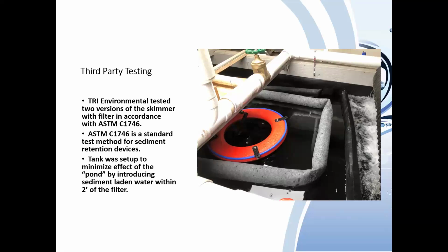You've got a forebay, you've got travel distance, you may have vegetation, you've got a lot of different things that can assist in that pond functioning to remove the sediment. It would be very difficult to determine what portion of the removal came from each part of the pond.